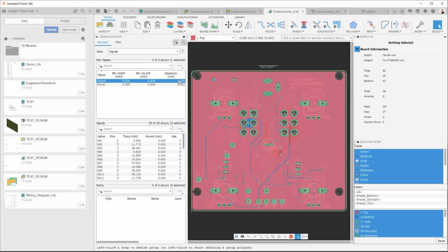Okay, cool. So what you're going to find is when working with Eagle, we basically had two types of library. You had the local unmanaged library that had no 3D content in it whatsoever. And then you had your managed libraries, which would get uploaded to the cloud and were the mechanism through which you could have 3D content that Fusion could use.